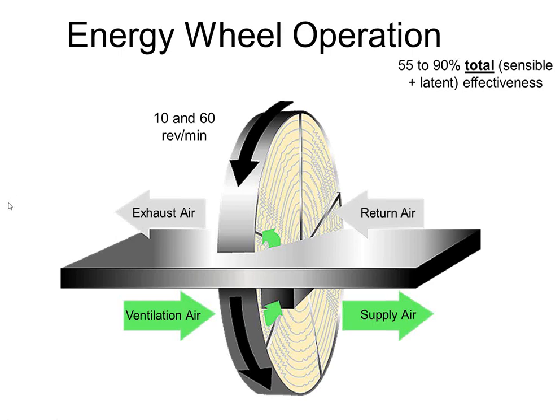Gil asks on that 12,000 CFM example if that was a wheel integrated unit or outside the unit. It was outside. It was a packaged rooftop unit bolted to an ERV, and I'll show you some pictures of that in a little bit. But that really is the most cost-effective scenario.